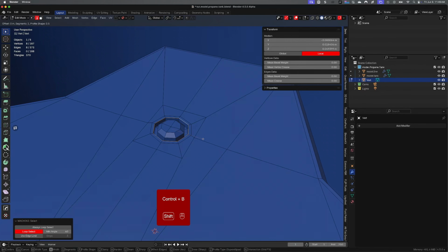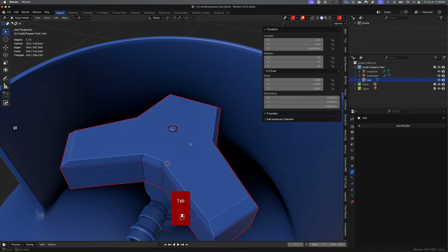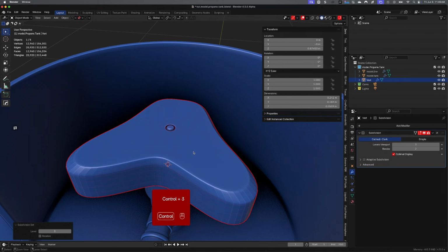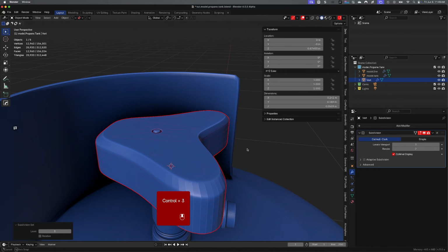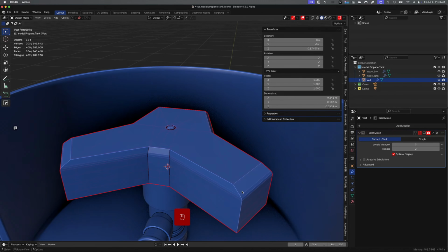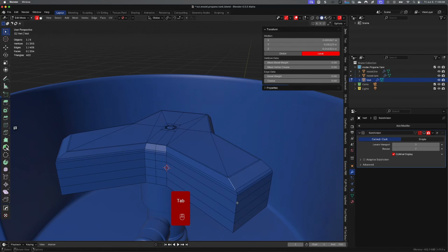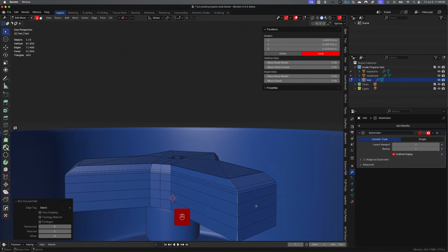So when we run sub D, it's going to look like a little screw there. I mean, we're not going to have a screw head in it, but it'll look like a screw. See? Imagine sub D on that. See, now nice, perfectly round. However, my issue is when you look at it from top ortho, it's not centered where the fitting is. But I'm going to show you how to fix that without having to model it again.